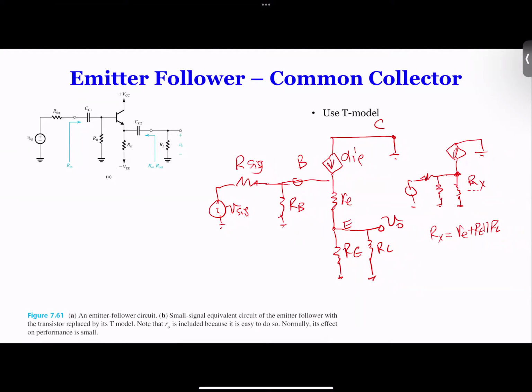So once you get this in parallel, and then you have voltage here, now it's easier to calculate the voltage over here. But remember, this is not a voltage divider. The reason is you have a current flowing here. The most common mistake that our students make is, oh, these two in parallel, easy, and this, oh, maybe in series, a voltage divider. You're totally wrong, because it's not a voltage divider, because there's current flowing here. Actually, the voltage drop here is much larger than the voltage over here. That's one thing to be very careful about.